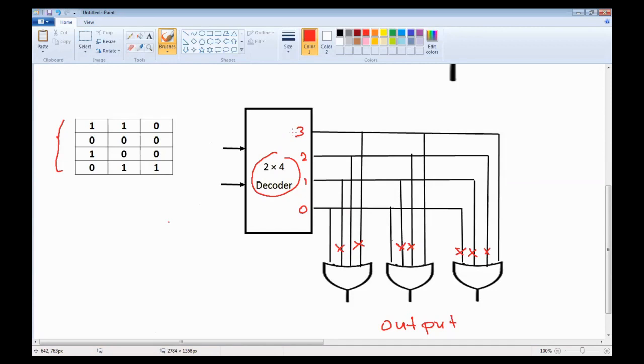For example, if we apply the address 10, so we'll have here 1 and all the other outputs of the decoder zeros. This one is transferred here, and it is 0 here, and here 0. So this is the output, and the address of this location 10 is read to the output as 100. In this way, during the manufacturing process, ROM is programmed to store the desired contents.